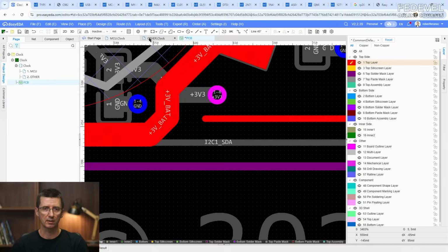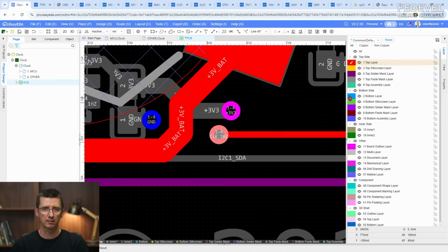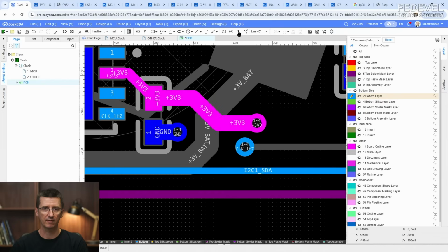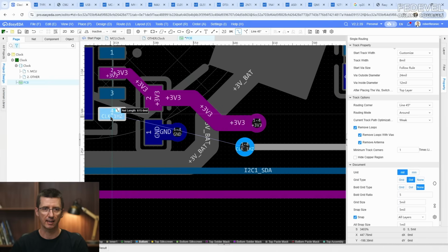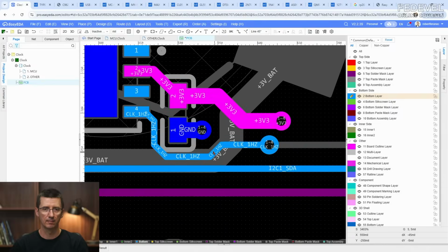So this is going to be the 1 Hz signal coming from the real-time clock. And it is very precise. It's more precise than running the clock directly just from the microcontroller. That's why I decided to route this 1 Hz signal.